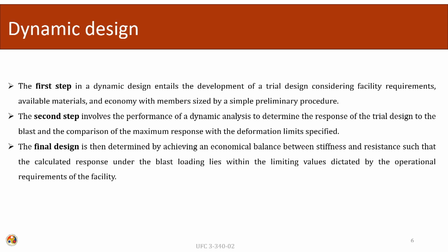Dynamic design. How to design this system? The first step in dynamic design entails the development of a trial design considering facility requirements, available materials and economy, with members sized by a simple preliminary procedure. So, a first trial is required, depending upon the requirement of the facility, the uses of the facility, the available materials and the economy that can be achieved by the existing materials. So, a trial design method is first applied to get the initial configuration.